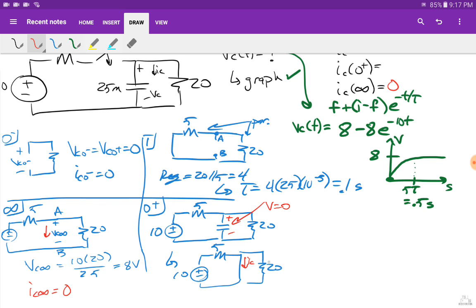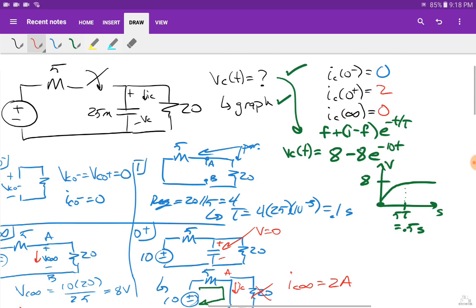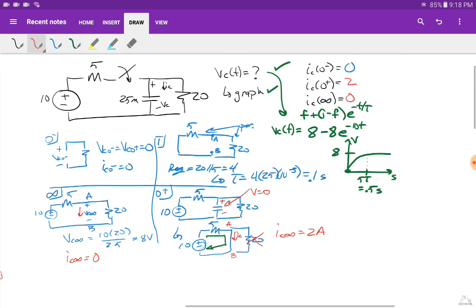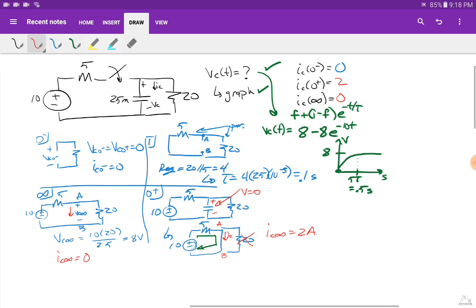Well, if you remember, because this is a resistor in parallel with the short, this being nodes A and B, this resistor is effectively killed, okay? And this circuit is all that remains. The current is going to take this path right here, just like that. So if this is 10 volts and that's 5 ohms, IC has to be 10 over 5, or 2 amps. And that would be our answer. So this is the solution to everything we needed in our first problem.